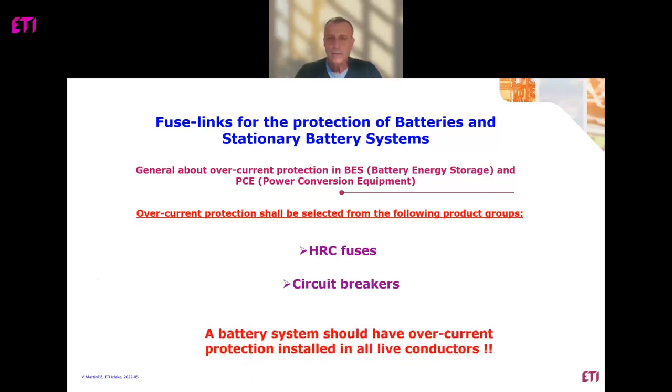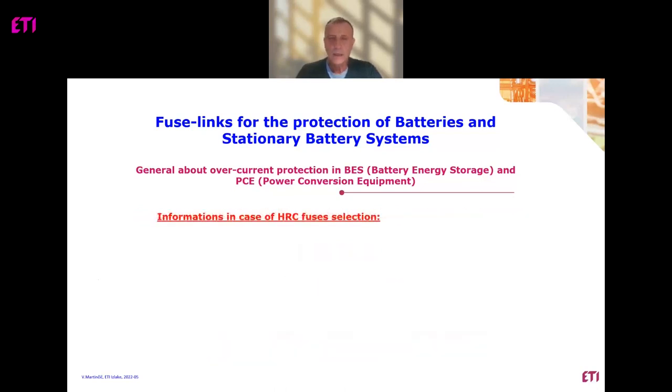And the most important is that the battery system should have overcurrent protection installed in all live conductors. It is very important, and we should not forget this. There is some information in case of high rupturing current fuses selection.